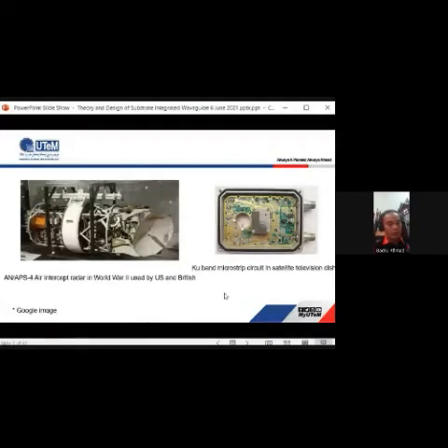It was used for satellite TV reception, which collects the radio waves from the dish and converts them to a signal, which is sent through a cable to the receivers inside the building. The LNB is a combination of a low noise mixer, oscillator, and IF amplifier. As you can see, it is a very small device but has multiple devices in it. It is very different from what you see on the left hand side, which is very bulky and big.